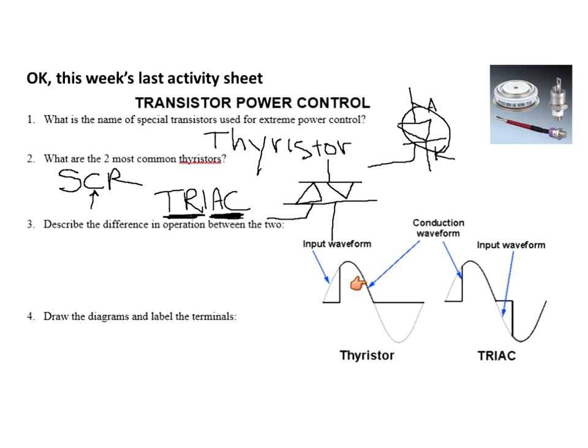That's called the conduction angle in there. But over here, look, I'm conducting here and there for the triac. So the triac can conduct both alternations. Interestingly enough, we use AC to power many SCRs, but what comes out of them for the load is actually DC. But it can still be used. Okay, next.